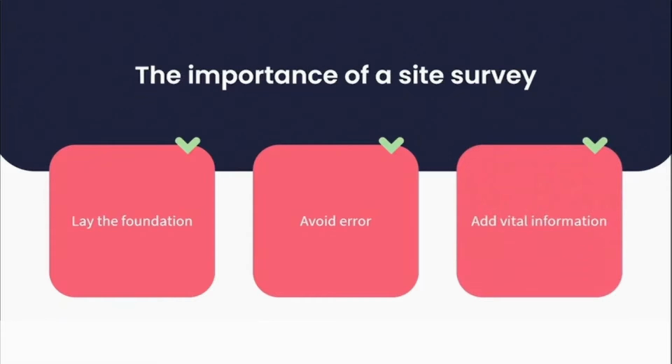And thirdly, the site survey is important as it provides vital information. A site survey provides accurate, current information about the site that you're working on and the site that you are currently standing on. The site survey will give you the best idea of the topography of the site, entry and exit points, obstacles that are in your way, resources that you might be able to use during the project planning or the project implementation stage, as well as neighboring developments, which I often find quite important. The survey will provide information about natural elements such as the sun and wind, which are vital factors when planning your project, planning entry points, planning openings, natural light points, etc.